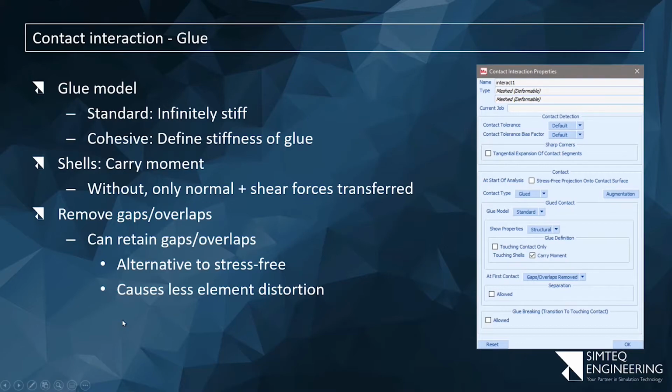So why on earth would I want to do something like that? And the reason is simply because I'm not moving the node, I'm not distorting the element in addition to anything else, in addition to the loads that I'm applying. This is something that you often see with second order elements. You start projecting or moving those nodes onto the face, and then suddenly the model doesn't want to run because it said some elements are inverted or something.